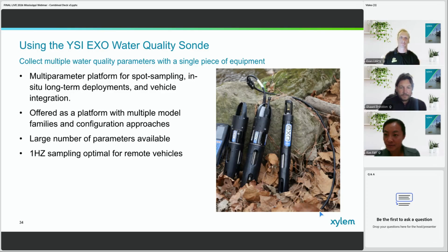Next question. Could you talk more about stationary boat measurements in moving bed conditions? That's an interesting question that we did not touch on in this webinar. Generally speaking, in moving bed conditions, many people will default to stationary as opposed to moving boat, and that is definitely an option. Stationary assumes, as the name implies, that you're actually stationary and taking station by station, kind of like a FlowTracker, measuring those velocities and averaging them at each station.